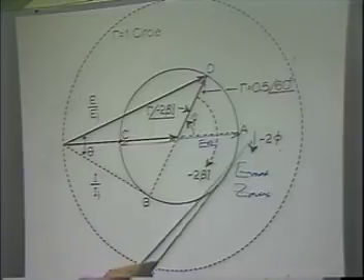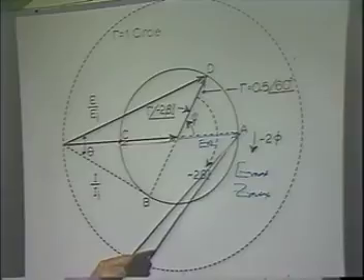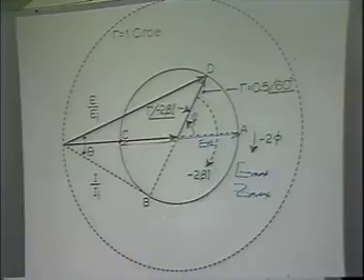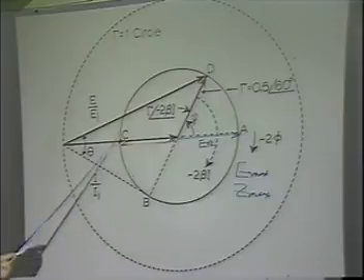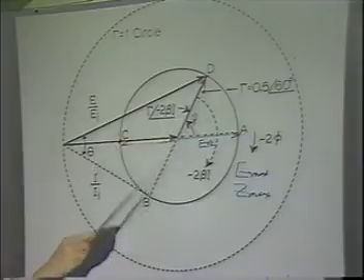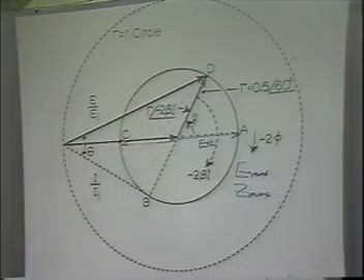So this angle here of minus 2 phi is only measured from this point here to this point here, in this case, all the way around here. So you subtracted out the original angle of the reflection coefficient of the load. That's all you did. Okay?